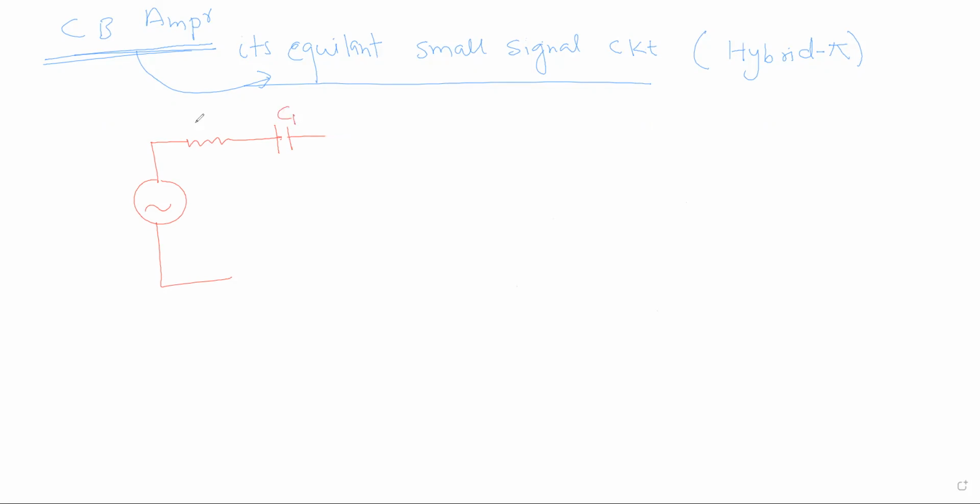This is the capacitor. Why do we use a capacitor here? That is a blocking capacitor. Why do we use a blocking capacitor? To block DC, that is your biasing voltage, from mixing with your AC signal. The capacitor blocks that DC from mixing with AC.